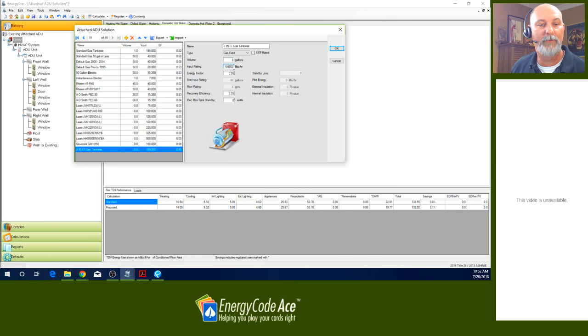One thing I like to bring to some consultants' attention, you may have run across this. If your input rating is 200,000 BTUs or less than 200,000 BTUs, it's considered a residential style or small tankless water heater. And that's fine. That's perfectly acceptable. It runs the analysis, shows compliance. The installer can put in whatever they want as long as the BTU input rating is less than 200,000 BTUs and the energy factor meets or exceeds that value. Technically, that's an acceptable water heater.